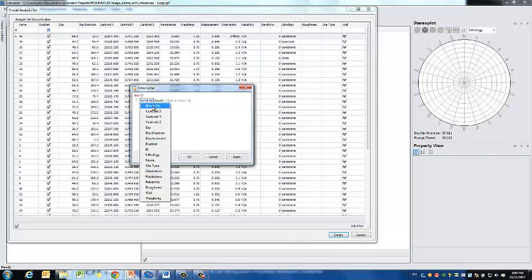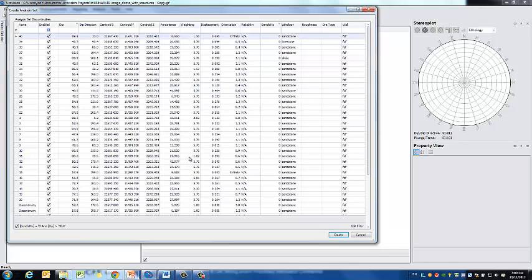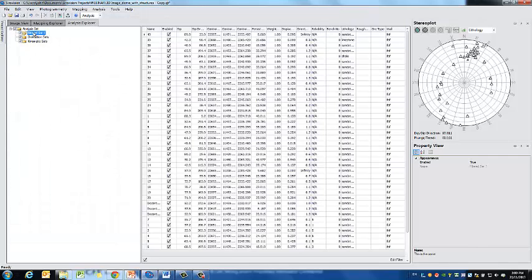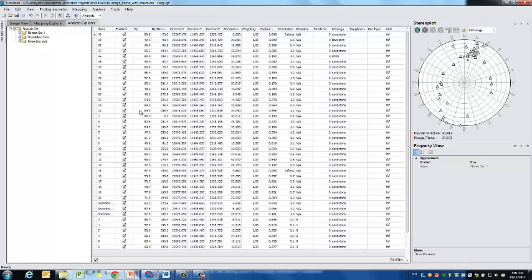So in this case, I just want to pick out everything which is on bench number 0, and give me everything with a dip angle which is greater than 40 degrees. So you can build as big an equation as you want and pull out whatever data you like. So let's apply that. That's pulled out most of the data. So this is a set, and here's the criteria I used to build that set. So create that set. So now I've got my filtered set listed here, and again in tabular form. I have all the data attached to those structures.